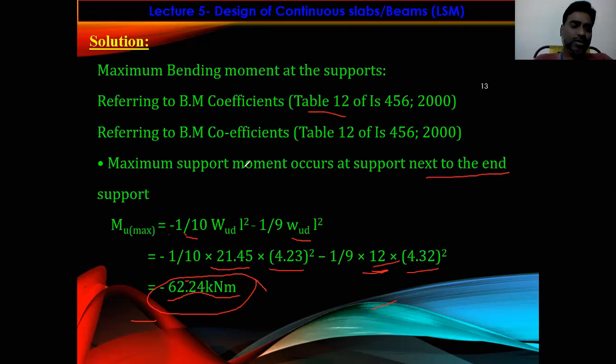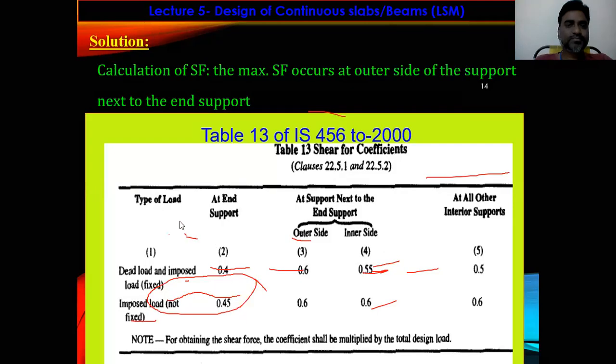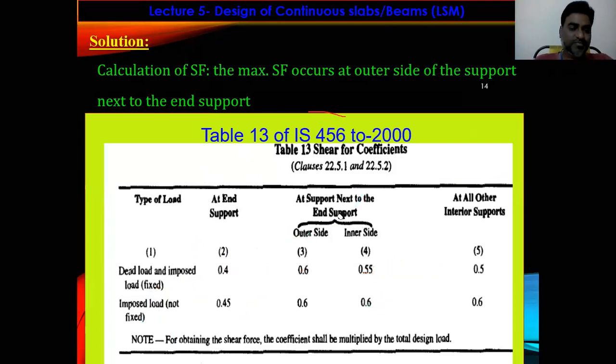Right? So like this, you have to determine the maximum bending moment. Similarly, you can determine the shear force also, where you will get the maximum shear force. So for the same data, for determining the maximum shear force, you need to use Table 13 as per IS 456.